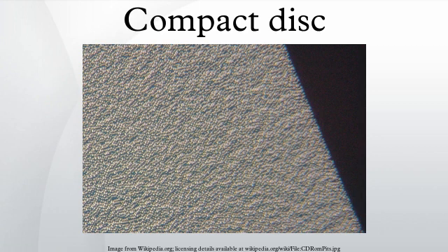Compact Disc Plus Graphics is a special audio compact disc that contains graphics data in addition to the audio data on the disc. The disc can be played on a regular audio CD player, but when played on a special CD+G player, can output a graphics signal. These graphics are almost exclusively used to display lyrics on a television set for karaoke performers to sing along with. The CD+G format takes advantage of the channels R through W. These 6 bits store the graphics information.